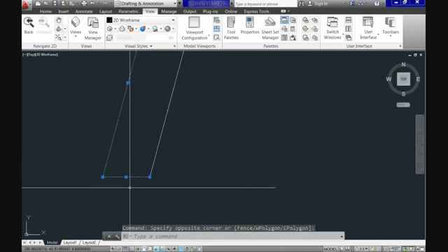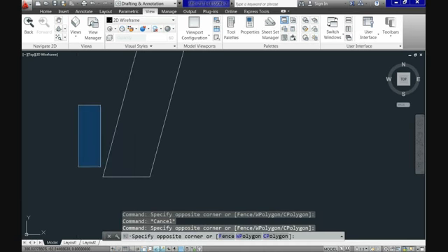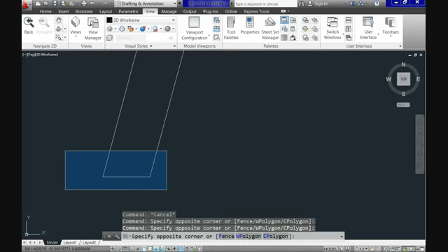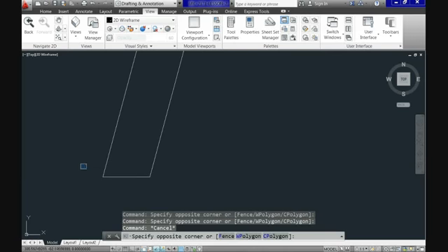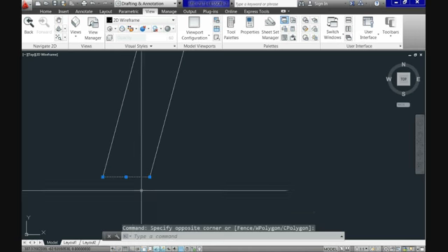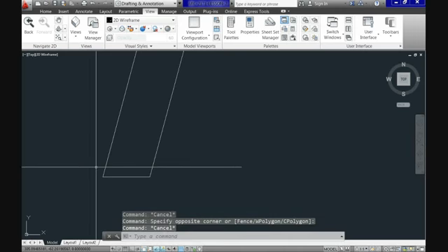But if you select from left to right, it only selects the elements which are enclosed in the window you select. This difference in selection is very useful when you're going to move things or copy things, or simply for the daily tasks in AutoCAD. You will see it later.